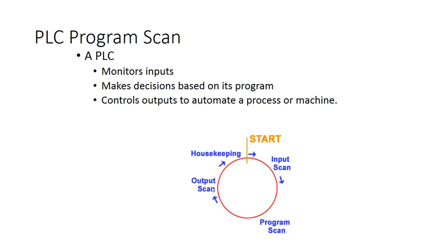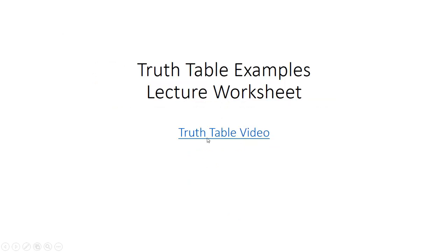So then the outputs turn on or off, and the outputs could be connected to lights and solenoids and everything like that, or these outputs could be connected to internal bits, and we'll do that. And then it keeps going: inputs, ladder logic, outputs, inputs, ladder logic, outputs. There's a little bit of housekeeping that goes on here just to be sure that the scan cycle continues to run.